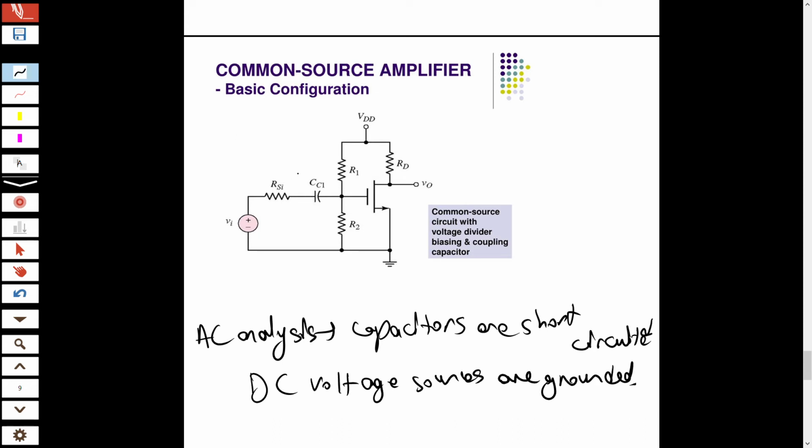So this is short-circuited and VDD is here grounded. So in the DC case, my circuit becomes: here is my V input signal, there is RS, it comes, R1 goes to ground this way, R2 is grounded this way, so R1 will be parallel to R2.